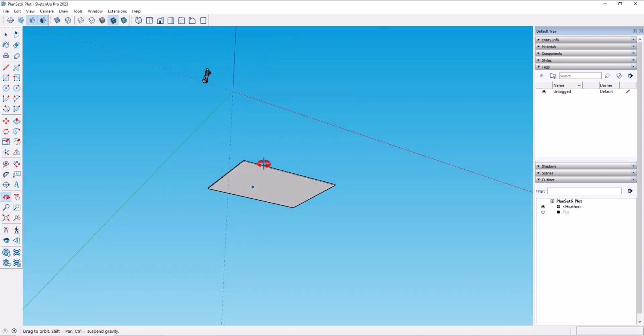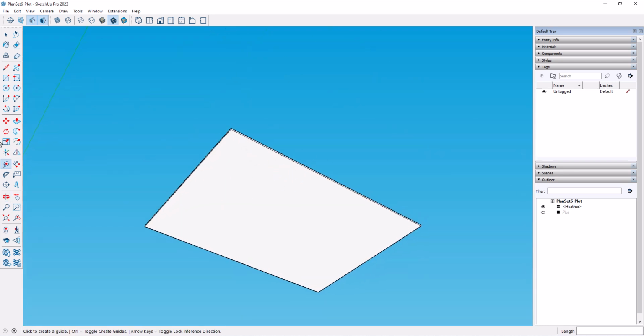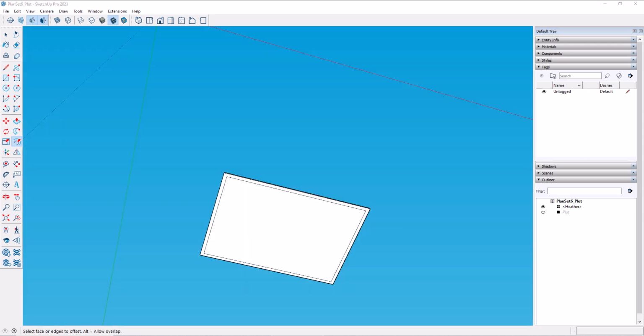Next, okay, we're going to go underneath. We're going to select our offset tool. We're going to click on the center, and we're going to type in 12, hit enter. And this creates our overall footing on the outsides. So there's the outside footings. Now we need to place where the center footings are on the inside that goes underneath our walls.